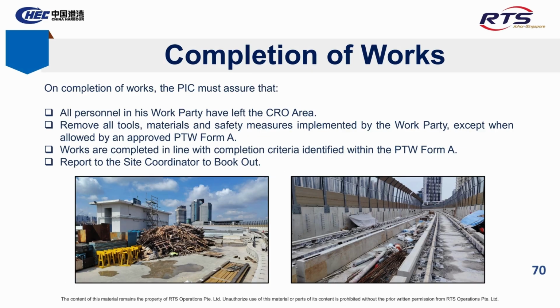Slide 70. Completion of works. PIC must ensure all personnel have exited the CRO area. All tools and safety items are removed unless approved. Work meets PTW Form A criteria. Bookout is reported to the site coordinator.